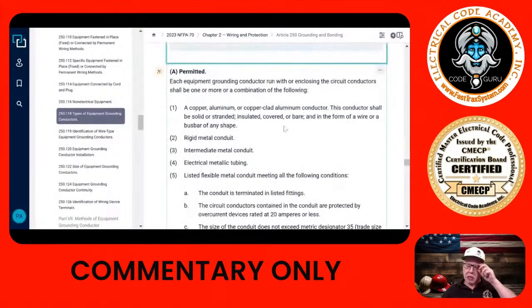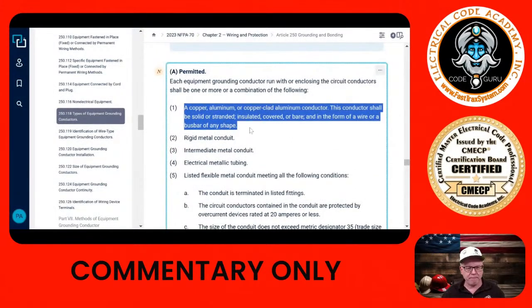All right, so they didn't run a conductor in there. Okay, so that's an issue. Now, maybe they have the ability to put this conductor in there. Okay, we'll see. But it's not going to be in some of these cable methods. It's not going to work. So let's see what we've got. All right, no conductors run, so we don't have an equipment ground.